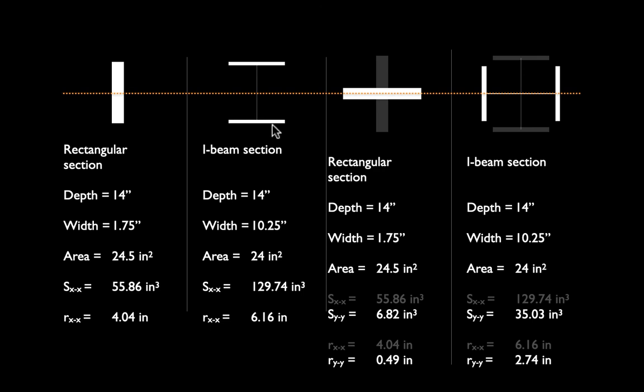If we flip that around and do a flat beam, exactly the same bit of steel, we find that we're only getting about 10% of the strength in bending. This explains right here why flat beams are worse than deep beams. And if we do an I-beam section there, we're gaining a little bit because the flanges are tall, so we're getting back some depth. But notice that the section modulus is still much less than if we do an I-beam in the correct orientation.